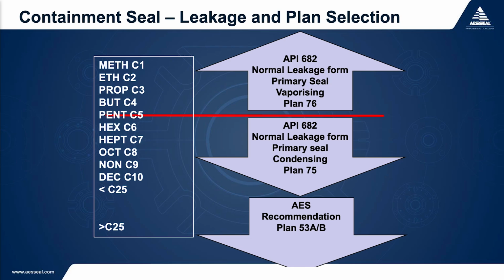It is most probable that this will be a C5 hydrocarbon or heavier depending on the minimum ambient temperature and the flare back pressure. Therefore, we consider mixed phase. For example, an overhead reflux pump will always have some small percentage of heavier liquids which will condense.